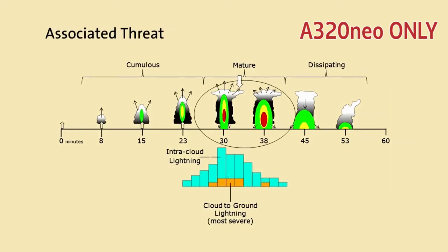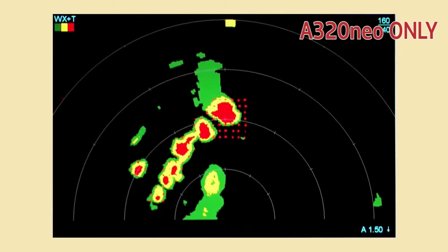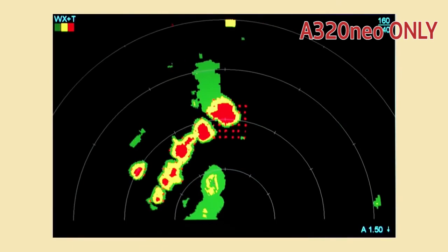In addition, at cruise levels, hail may be thrown out of the top or sides of the cell and in the downwind direction. ThreatTrack's Associated Threat feature provides flight crews with a mid-altitude associated threat, a mature cell associated threat, and an anvil top associated threat that correspond to each of these 3 scenarios. The following is an overview of the 3 associated threat warnings.